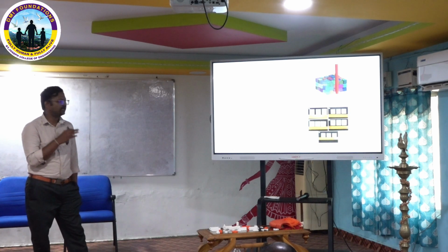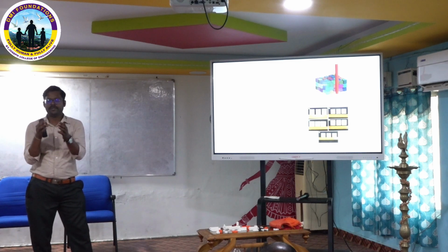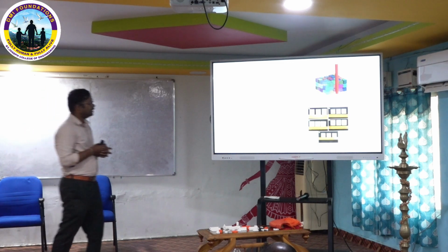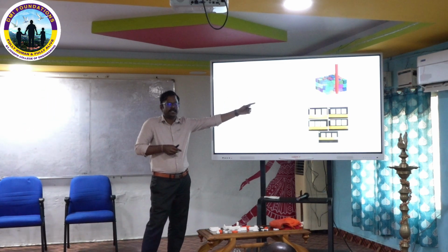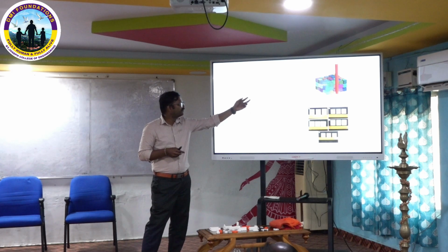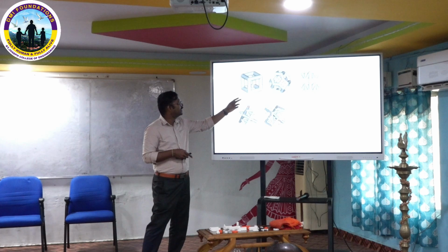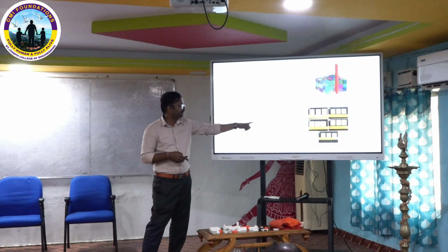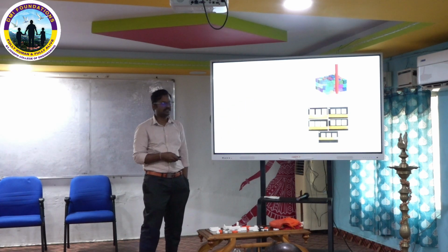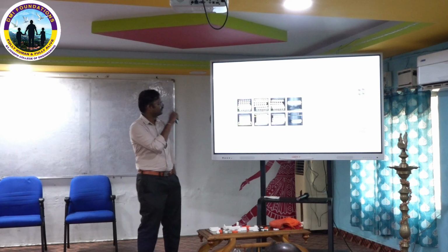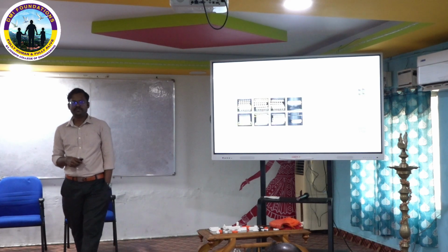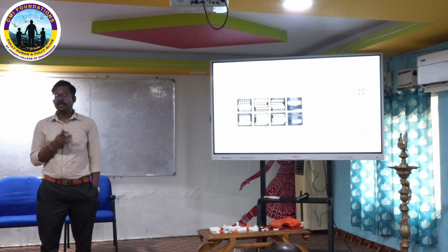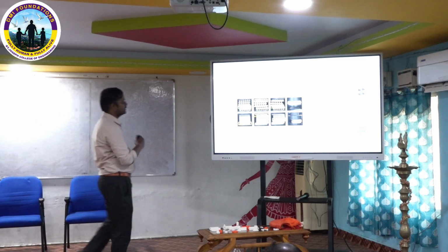So we have to learn which relative density is best for my application. So what I did, I selected 10, 20 and 30 relative density, and for all 5 unit cells I designed my lattices and fabricated them with this Taguchi analysis. Then each and everything I compressed with different unit cells. Around 150 lattices I fabricated, printed and tested.